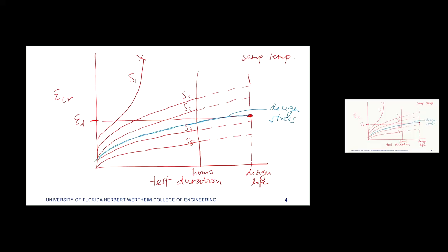Unfortunately, you cannot really figure out what's going on with these kinds of tests without doing this entire suite of testing at multiple temperature levels. So this is isothermal. It's a standard creep test. We're just extrapolating out in time, putting some hard constraints on it and saying, okay, what's our maximum stress we should use in order to not exceed those things for this particular application. So that's the abridged method.